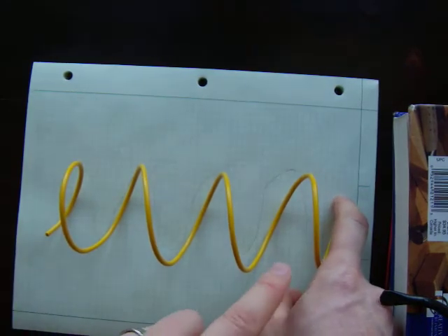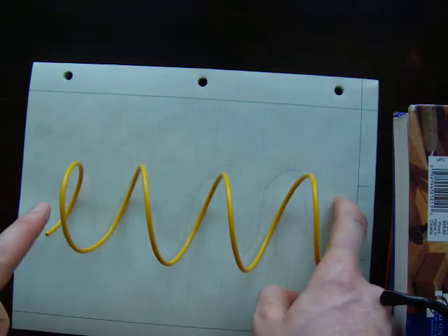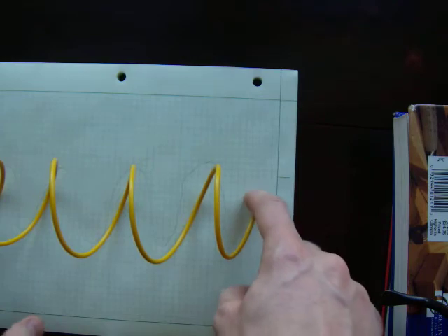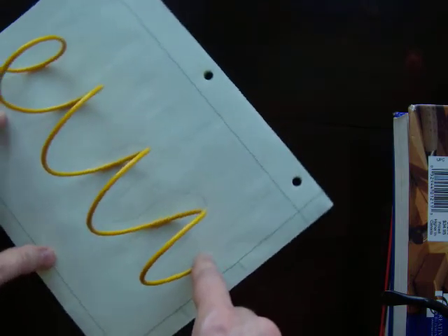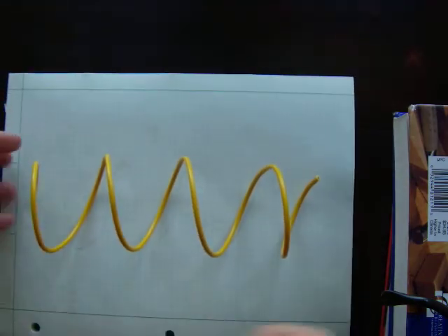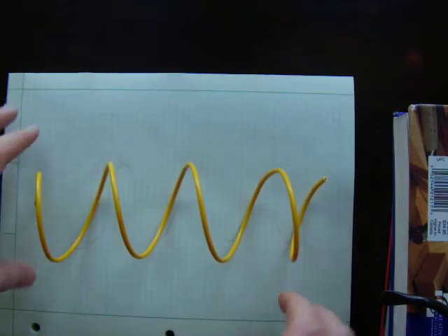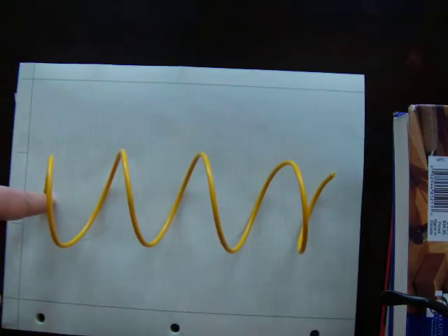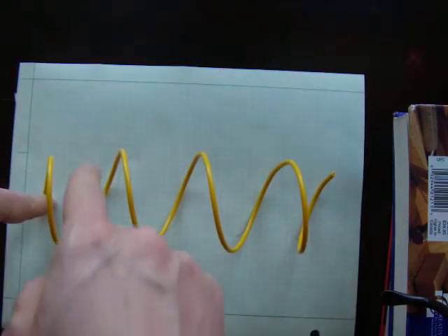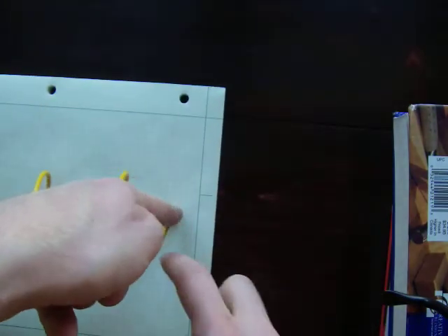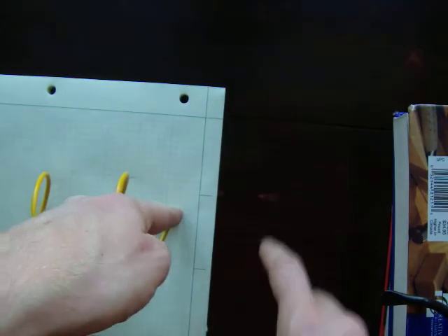What we see is that this one has not just been flipped. It has been flipped, but it's also been inverted, because the sinusoid was inverted in the time flip. So a flip along the time axis results in an inversion on the imaginary axis. Does that make sense? Originally we were going down, then up, then down, and when we flip it around and look at it, we would continue this on. Now it's going to start to go up, and then down, and then up.